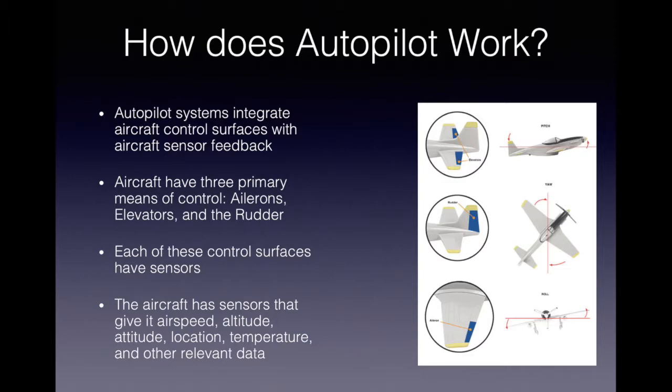The pilot can set a desired altitude into the autopilot, and from there, information about the aircraft's instantaneous altitude and vertical speed is pulled from the corresponding sensors and used to calculate the required elevator deflection angle to get to and hold the desired altitude. This can also be applied to hold a specific heading using aileron and rudder deflection, but for the remainder of this video, we'll focus on the single axis case, holding altitude with elevator pitch.